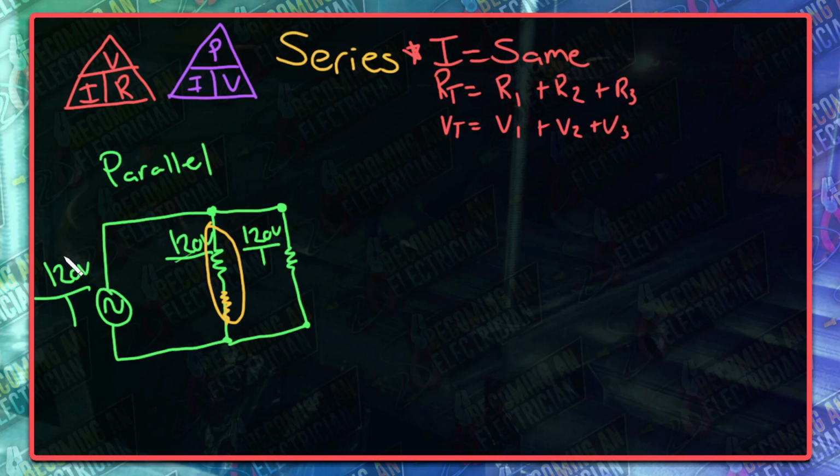And so when we have our source, which is 120 volts from the panel, which is just one circuit and a neutral, then each plug or each light is getting 120 volts. That way, every light, every device is getting the required voltage, which means that it's going to get its proper brightness. In a series circuit, again, even if it's AC, let's say we have 120 volts.